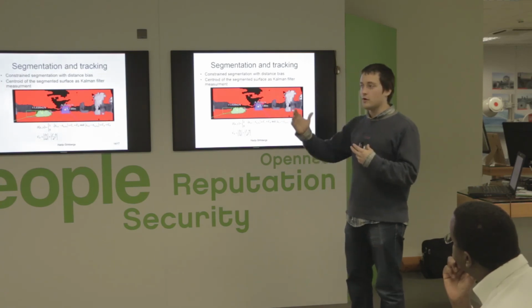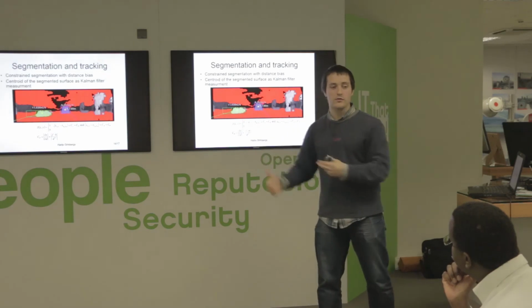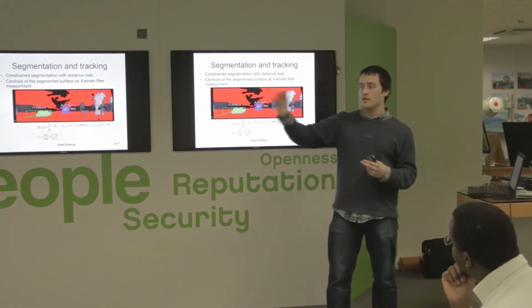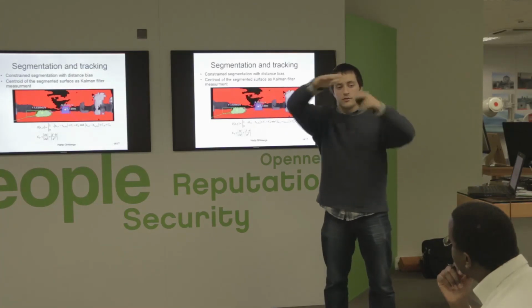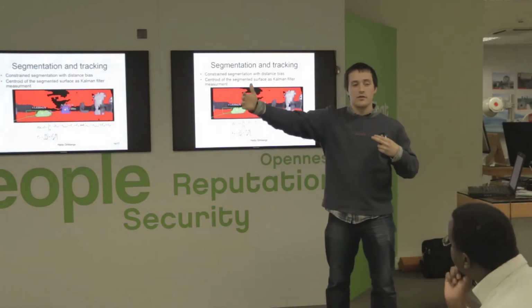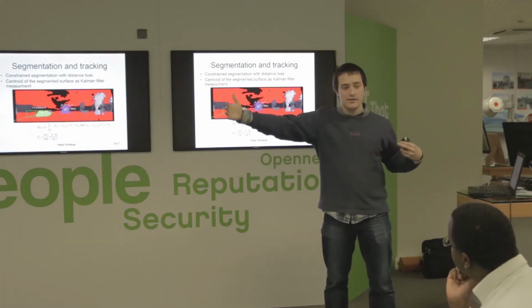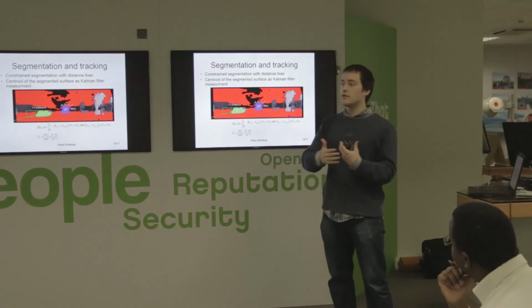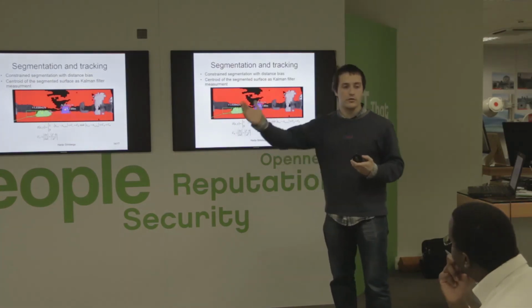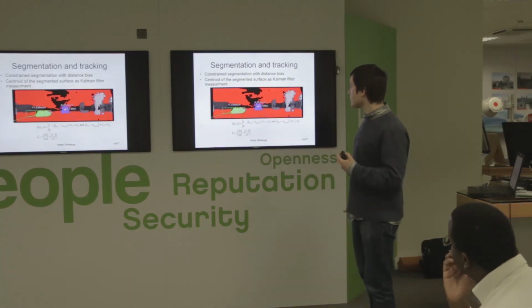So if I wanted to track a car at that distance, I couldn't say segment everything in a 2 meter Z region, because the error itself is more than 10 meters at that point. So the car is actually 10 meters long at that distance. I had to take that into account if I wanted to track at those distances.